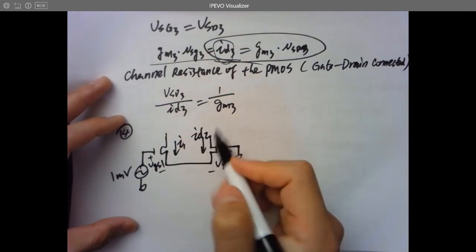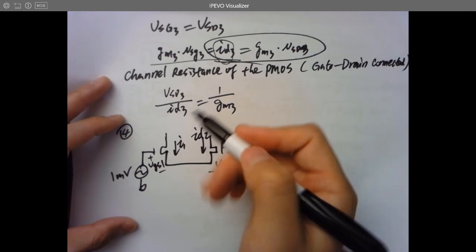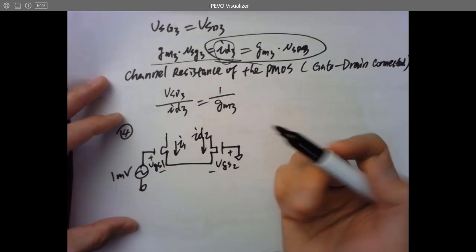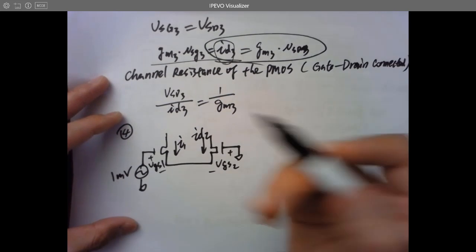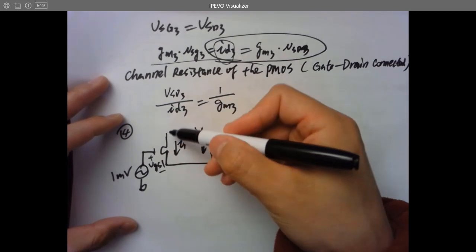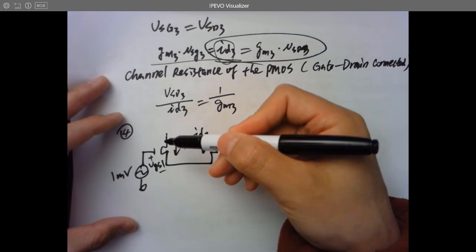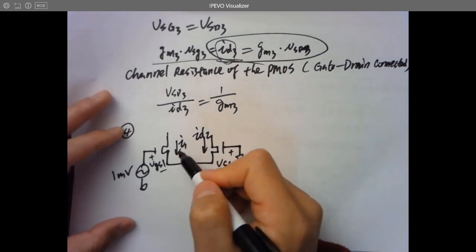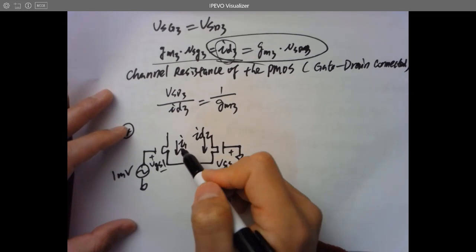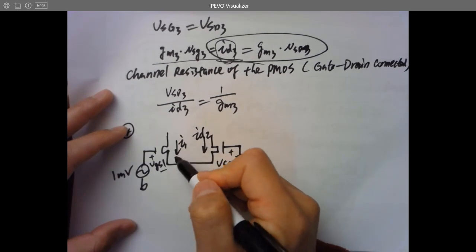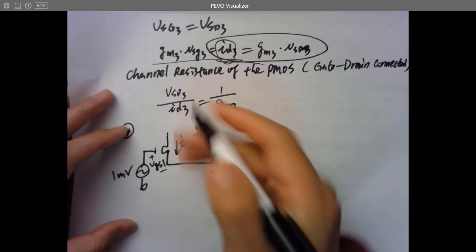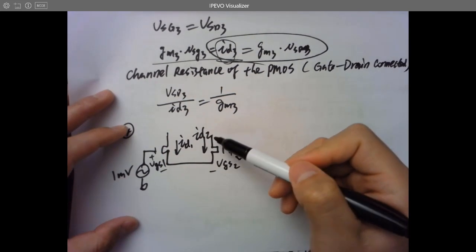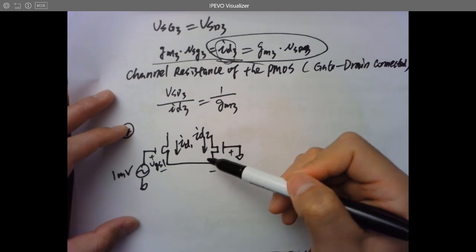And you're asking why you don't draw the top part. For this part, it's just a resistor, right? You can draw it if you like, but it's the same AC current oscillating in the same channel, just one channel, same current. We assign the polarity of the AC current from top to bottom to be positive for ID1, and for ID2 also from top to bottom is positive.